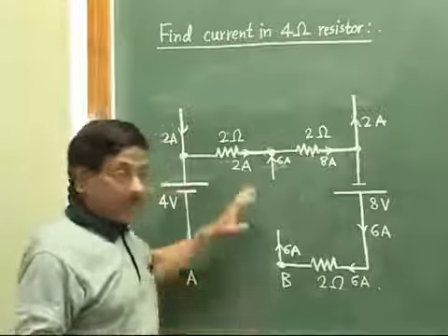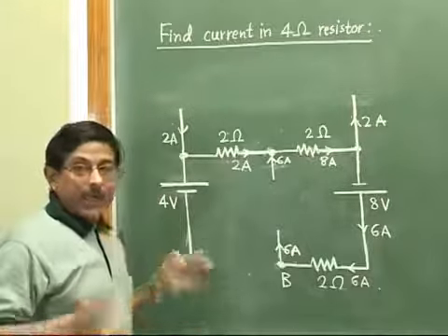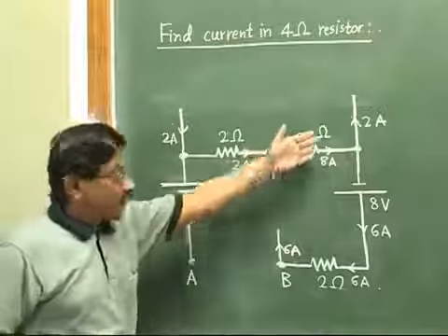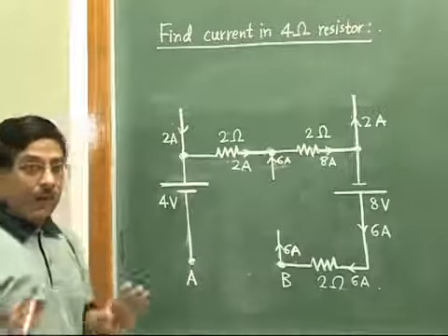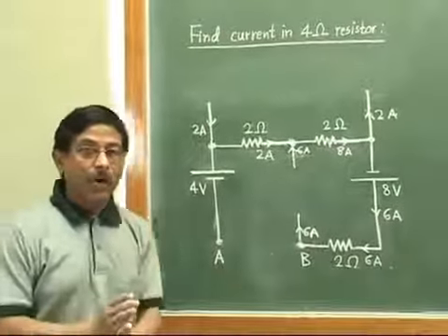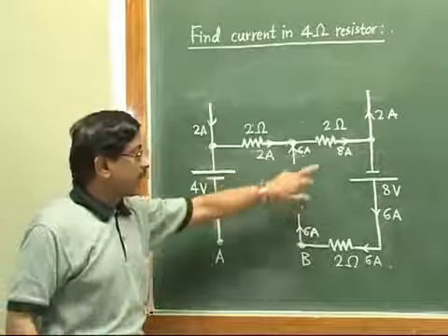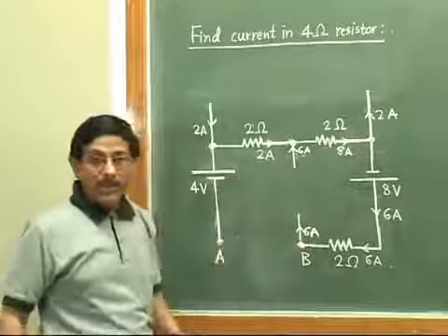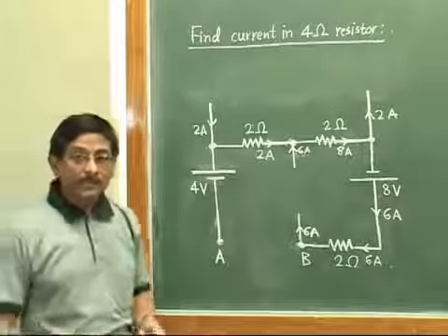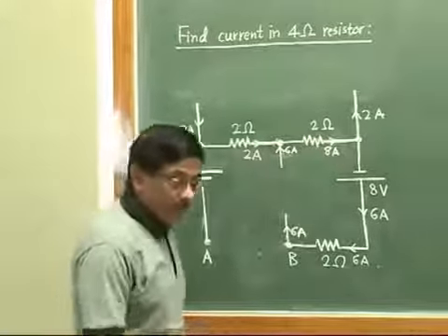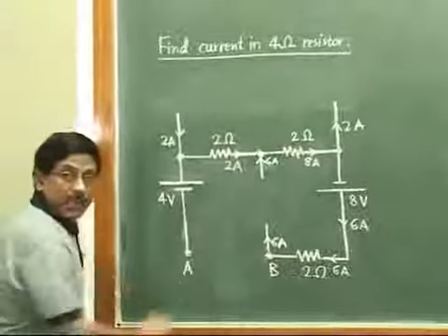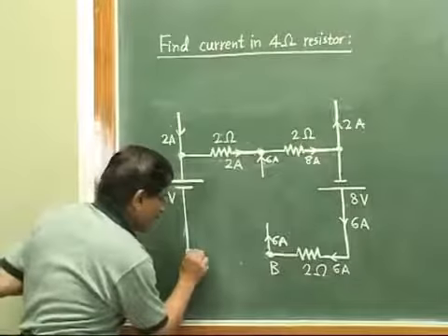Of course, for this circuit, we did not require to assume any current variable, because the problem is solved. What we want finally is to distribute the current and find out various branch currents. That only we want in the second step. So that we have done. We know now all the branch currents. And further, the next or third step is to find VTH. How to find VTH? We have to assume a fictitious or imaginary voltage source across the open terminals. Suppose I assume it like this.